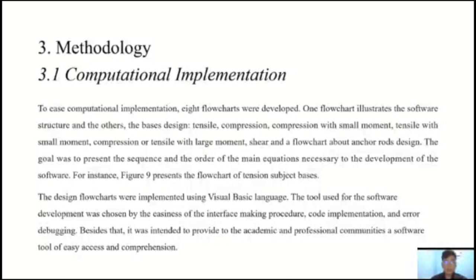3. Methodology. 3.1 Computational Implementation. To ease computational implementation, 8 flowcharts were developed. One flowchart illustrates the software structure and the others the base design: tensile, compression, compression with small moment, tensile with small moment, compression or tensile with large moment, shear, and a flowchart about anchor rods design. The goal was to present the sequence in the order of the main equations necessary to the development of the software. For instance, figure 9 represents the flowchart of tension subject bases.